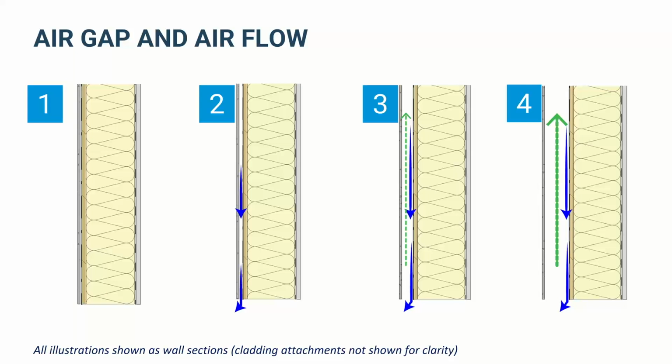And the other is tolerance. We're not expecting these walls to be perfectly flat. We're not expecting the cladding to be perfectly flat. So there are going to be some tolerance issues we need to accommodate. You might actually see a larger cavity designed for things like brick, where we're expecting a pretty decent amount of mortar buildup. Mortar can fall in that cavity and really block it. So larger cavities are typically designed for things like that, just to accommodate construction tolerances in the field.